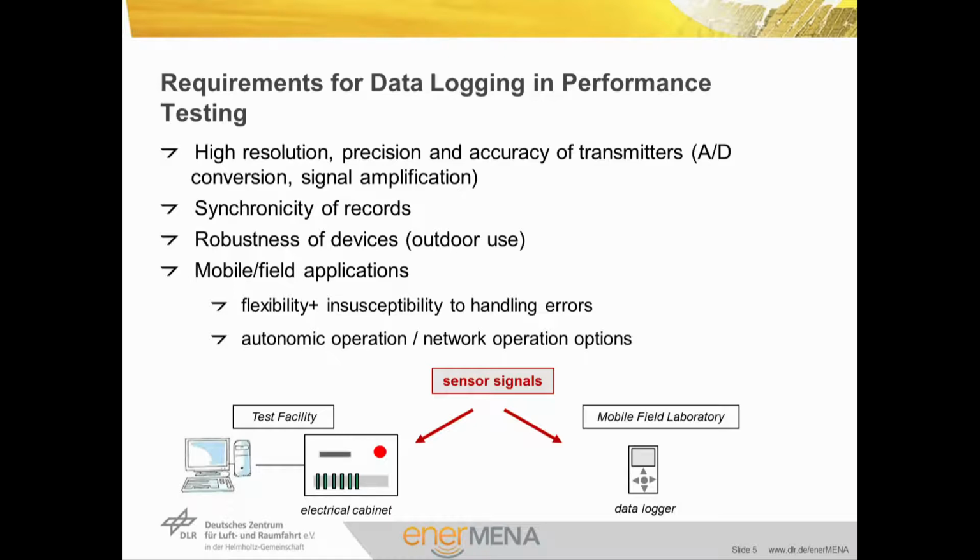As the time serves as a reference base relating measurements during performance measurements, the synchronicity of records is one of the most important requirements for successful data analysis. If more than one recording device is involved, for example in the case of several loggers or logger and plant control, the internal clocks must be brought to agreement to provide a consistent time base for measurement data.